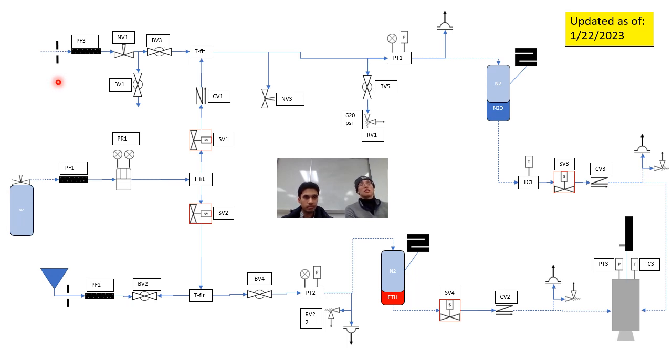We also want to limit anything that could cause a spark, which is why we have those particulate filters again. So we purge. The whole purpose of this filling with nitrogen and this purge process is that we're trying to get rid of the atmosphere, because the atmosphere itself could be seen as fuel for something as oxidizer heavy as liquid nitrous oxide. So we're eventually going to purge it, and then close valves as it's purging so that only nitrogen, which is an inert gas, is left inside of this whole feed system.